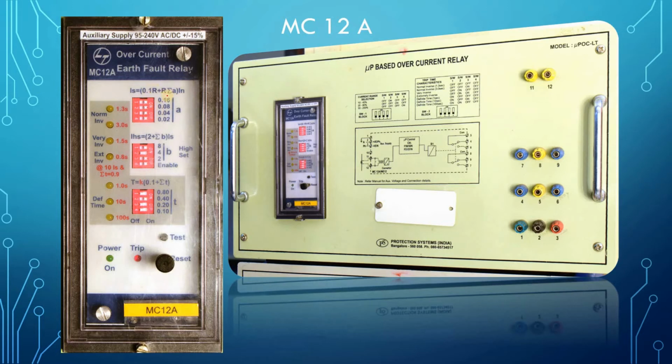And similarly, for the maximum IS we can set, R can be 5 and the summation of A can be 0.3. So how much will be 5 into 0.3? 5 into 0.3 will be 1.5, and 5 into 0.1 is 0.5. So 0.5 plus 1.5, that is 2. So maximum IS can be 2. That means the current setting ranges from 0.1 to 2 ampere.